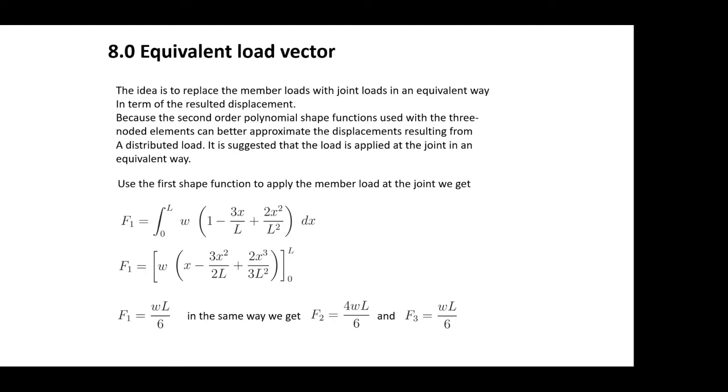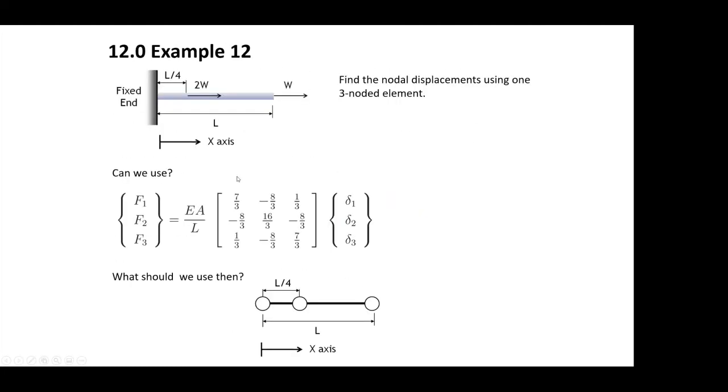Okay. Now, in this case, this is different. In this case, you have a concentrated load, and the concentrated load is by definition at this point here. I'm going to use my pen to put some marking on there. So by definition, this concentrated load is located at this node here. So you cannot control that. You don't have control over this. You are not making assumptions and assuming that this distributed load is lumped into nodes. What you have here is a load by definition located at 1/4 of the length. Okay?